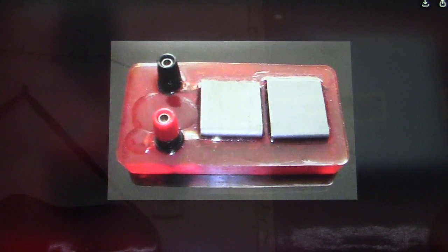Connect the cell to the pipeline and monitor any changes in the current. This is dynamic, so if you have somebody at the transformer rectifier to adjust the amount of current being discharged, this will show immediately whilst you are making this measurement.